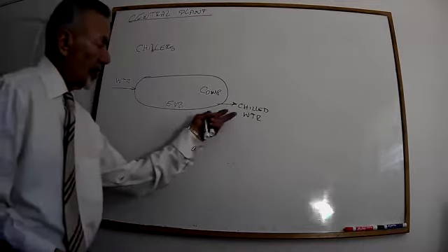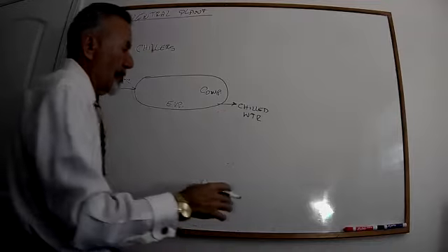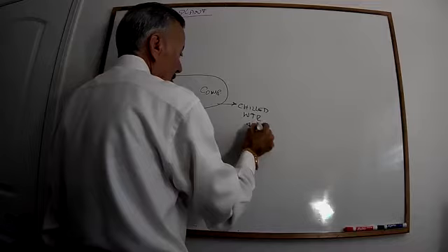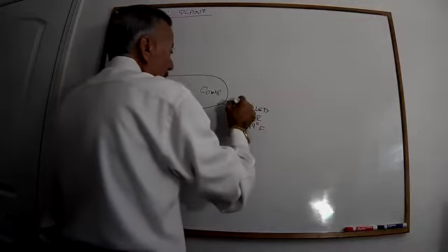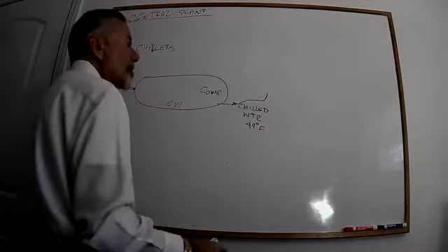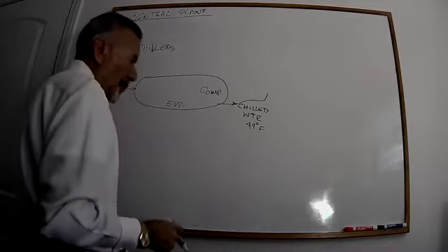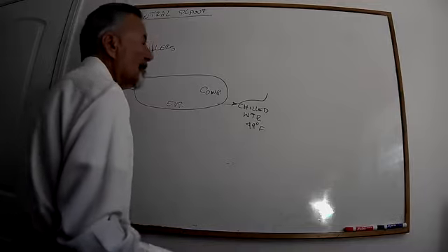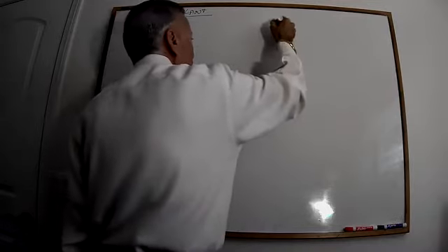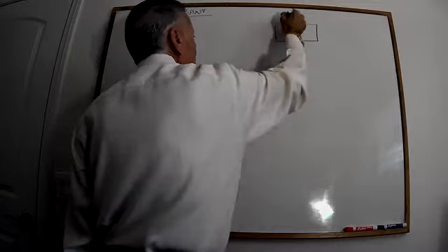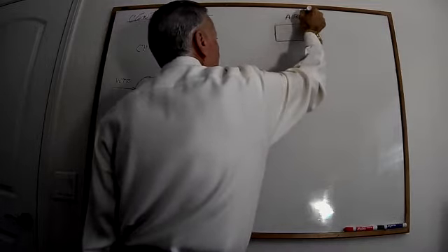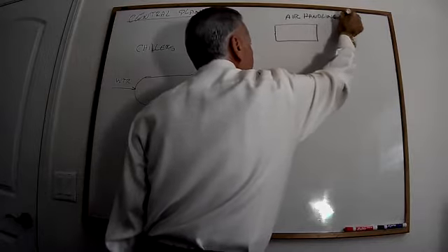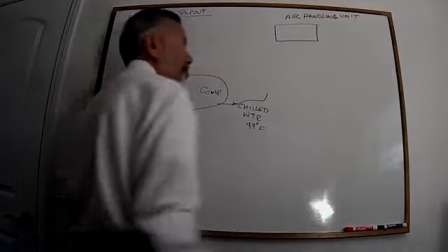Now, once you get that chilled water, you pipe that, you insulate it. This is about 49 degrees Fahrenheit temperature. And this goes to various buildings. If you look at the top floor on the roof of our own building, let's say ECS, you'll see a box that is called air handling unit, or AHU.